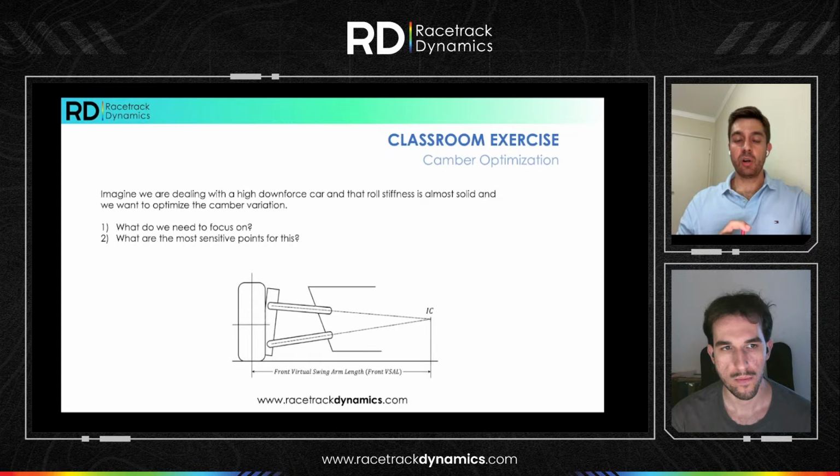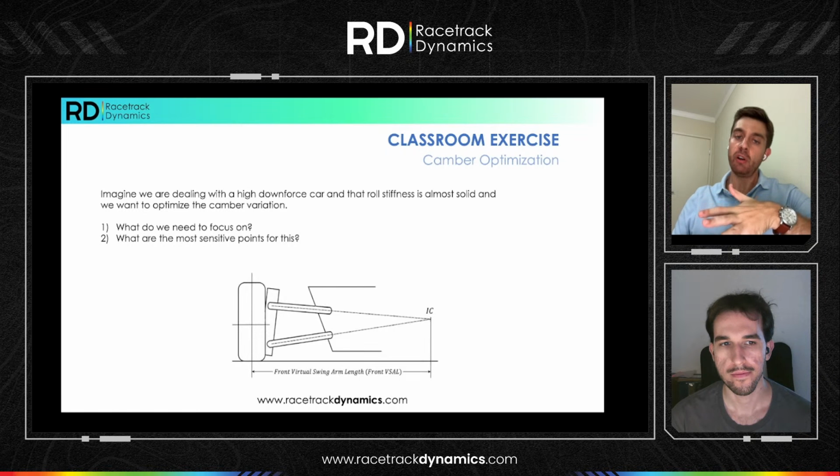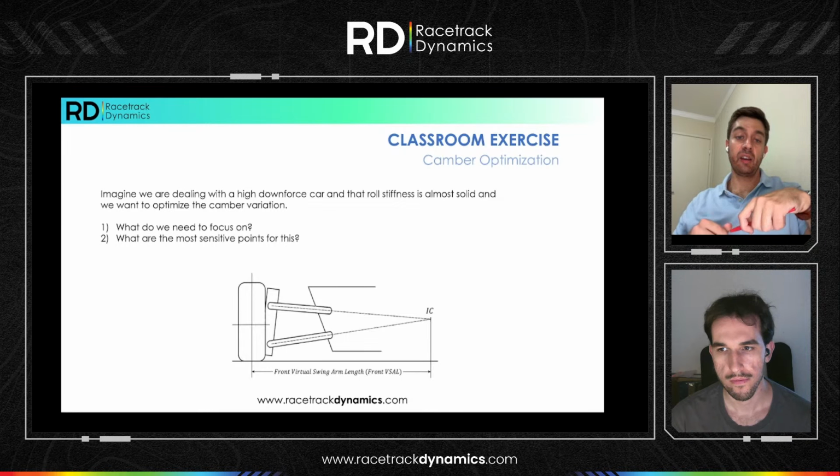So if we want to optimize for heave using our front view swing arm length, what do you think are the most sensitive points for this? Judging from the diagram, what are the most sensitive points that will have this effect? In other words, is it the tie rod location in X that is going to have an effect? Is it the outer ball joint in Y that is going to have a large effect? Is it the upper control arm inboard in Z that's going to have a large effect on what I'm trying to accomplish? So what are your thoughts?